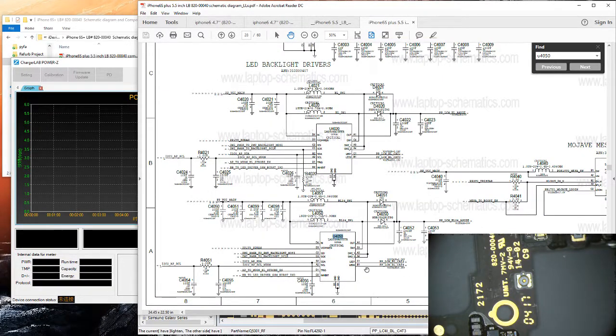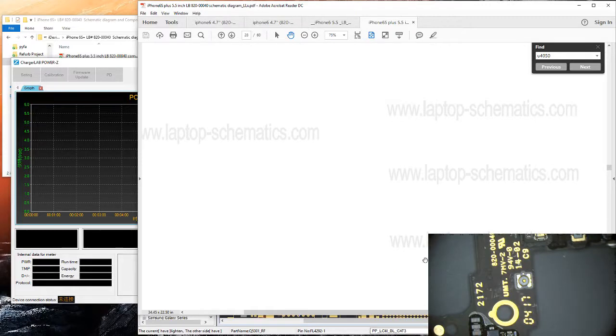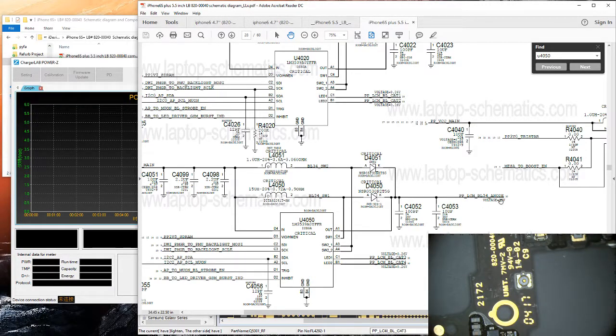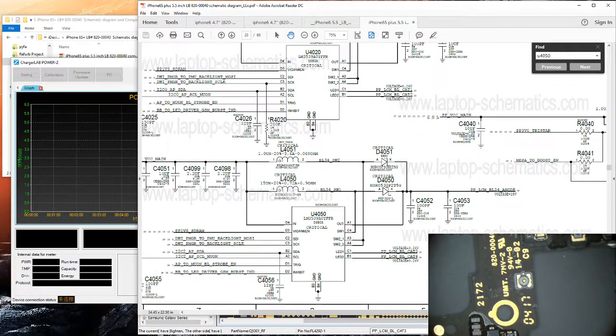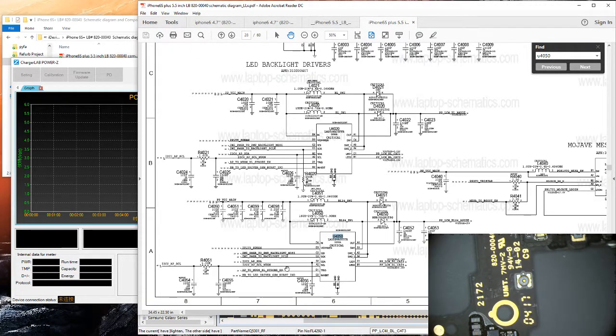Your cathodes here, you can see they come back in. They put voltage on here. 25 volts output on the anode, 0.26 volts coming back to the board on the cathode. Make sense? Capiche? Okay. So what could fail on this that would cause half of your backlight to go out?